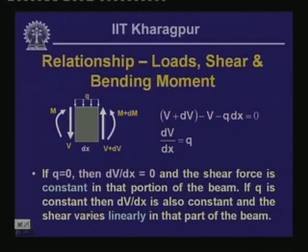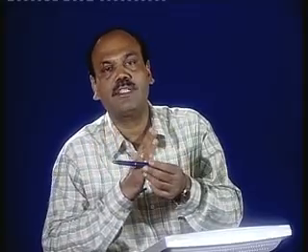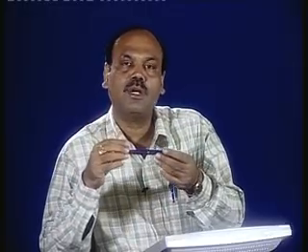Well, as I have told you last time, the basic objective of this kind of analysis on beams, when a beam is subjected to transverse loads, is finally to evaluate what is the stress this particular member is undergoing because of such loading and what is the deformation in the member. Now, to know precisely what is the stress level at any point and along the length of the beam, we need to know how these quantities, the stress resultants, the shear force, the axial force and the bending moment, are varying at different cross sections along the length of the beam based on the loadings it is subjected to.